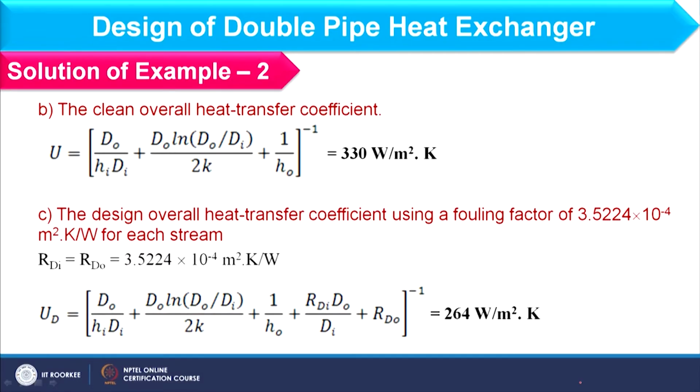Now, if you remember the last lecture, why am I calculating this wall temperature? Because it will give me the viscosity correction factor. That may not be required over here, but this is basically used to calculate the viscosity correction factor. Here different parameters you have to calculate whether they are connected to each other or not. So, average wall temperature we can find as 71.2 degree Celsius.